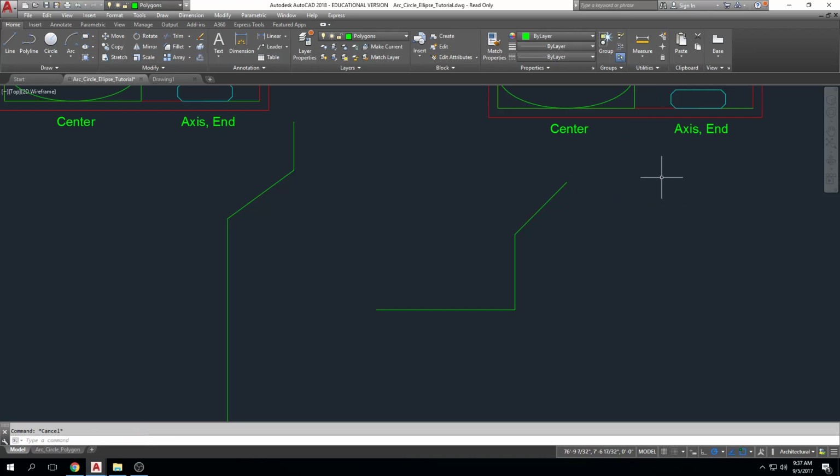One thing, again, we talked about this before, but I just don't want you to forget. As you're creating these, direct entry is obviously easiest, because you can see it's going this way instead of this way. So I prefer that method as well. But just remember, if you have an angle like this, and I'm just going to make this up so it's not right, but you're given an angle of like 35, that angle can be from this direction, but it also could be that other angle that you have to input to get it right. You're going to have to worry about that other angle when you do a direct or a polar or an absolute or whatever input. When you're doing direct entry, you get the polar tracking to snap, and then you go on. So it's a lot easier. But just remember, you have that other angle you have to worry about too.